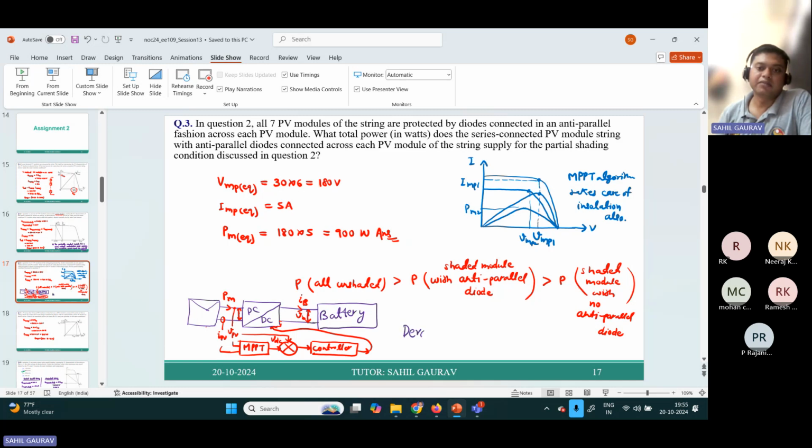So one term that comes up is derated MPPT. In Professor Bhim Singh sir's papers, you will find this term more frequently. You are not operating your PV at MPPT but at a lower value, below the MPPT value, because this converter will not operate at that duty cycle, as this voltage should be fixed.